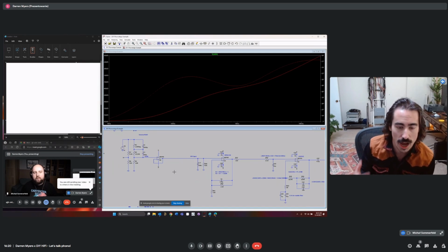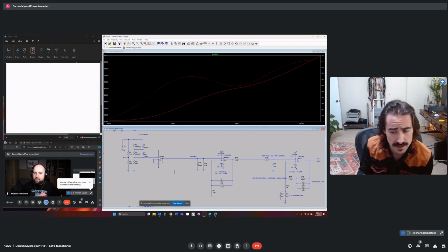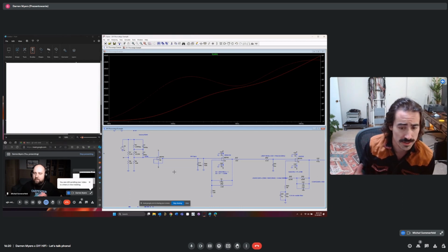But all of this was done to optimize the vinyl format. Without this, you wouldn't have very good performance. You would have maybe high THD at low frequency, or you would be dealing with skipping and jumping grooves when there was a lot of bass in the recording. So this is something that is necessary and was specified by engineers, and there are different curves like the Decca curve, but the RIAA curve was the one that was adopted widespread, and that's a whole other world.